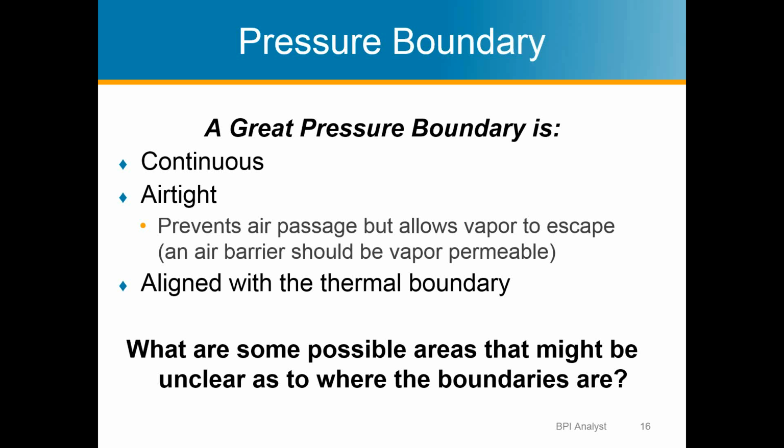when air leaks out of a building, the air has energy embodied inside of it. If it's in the winter time, it's got heat in it that's going out. So if the air is leaking out of the house, heat is leaving the house. It also has water in the air. And so as the air leaks out of the house, it's taking that water with it, which we talked about last week with dew point.